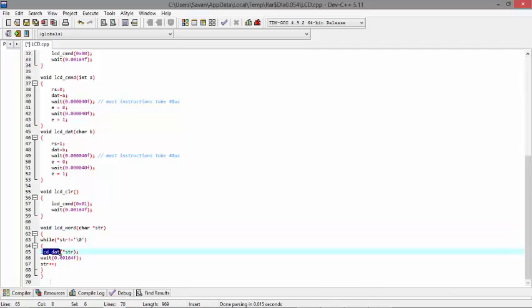Inside the function, it will call another function, that is LCD data. As we already saw the LCD command function, the next is the LCD data function, where I told what the RS pin does. So when it calls from here, it comes here, and I put the RS pin 1. Whatever I write inside the bracket, it will consider as the data that needs to be printed.